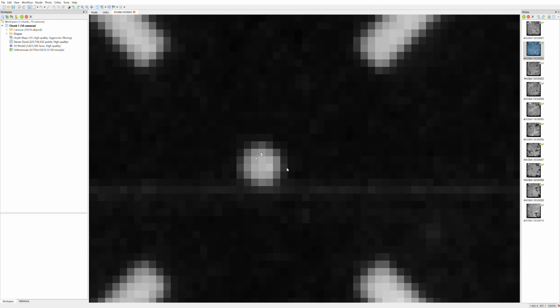And then you can press page down, and that'll go to the next image, and it'll be zoomed in at the same area around that X. And so now you can right click, and when you go to place fiducial, 1 will show up on your drop down list. So I'll just click 1 and put it there, and I'm going to page back up and place my number 1 here again.